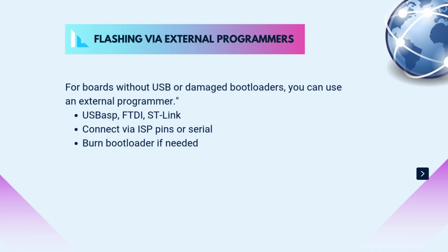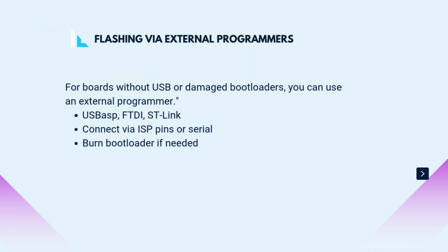They connect to your microcontroller using ISP or serial pins and allow you to upload code, burn bootloaders, and recover bricked chips. You simply connect the programmer to your board, make sure the pin mappings are correct, and use the IDE's burn bootloader or upload using programmer option. These tools are lifesavers in more advanced development and repair scenarios.